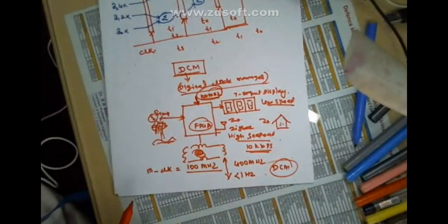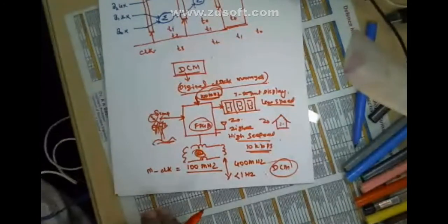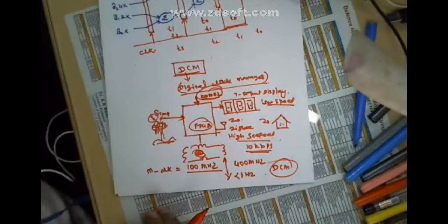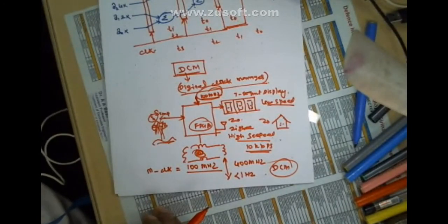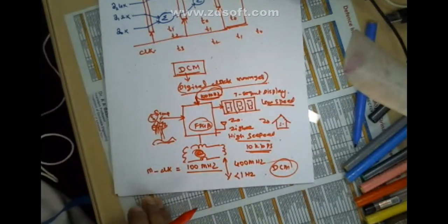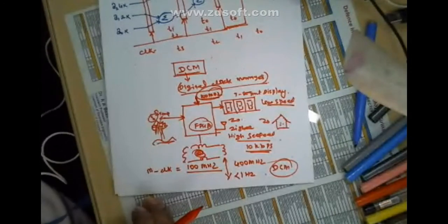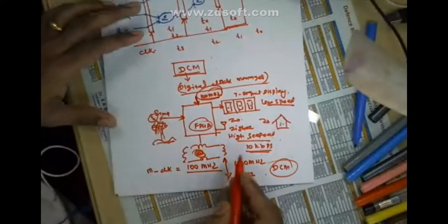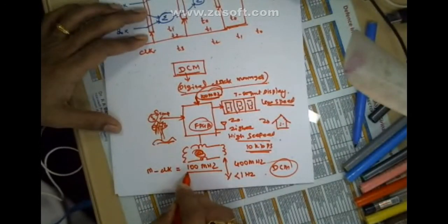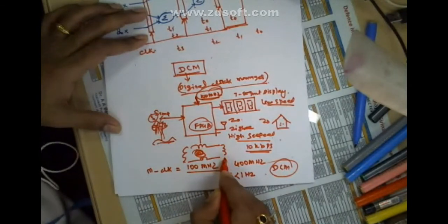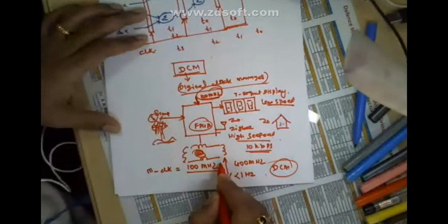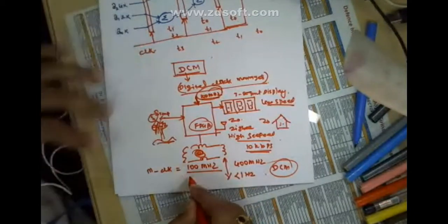Digital Clock Manager, now. The digital clock manager is a very essential unit in our design because you are feeding the onboard clock into it. That unit will generate 0.1 hertz, 1 hertz, 10 hertz, 400 megahertz, right? Increasing the frequency from 100 megahertz to 400 megahertz is called interpolation, upsampling.